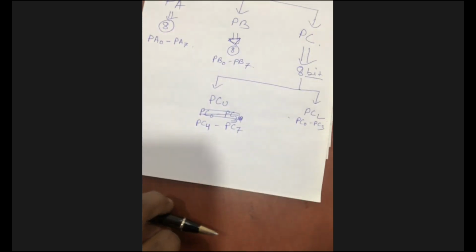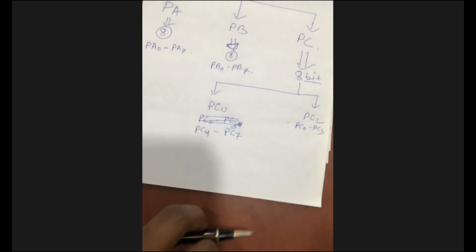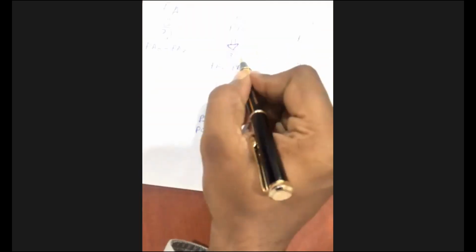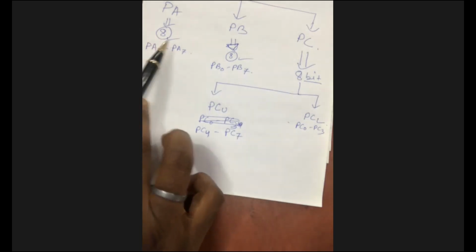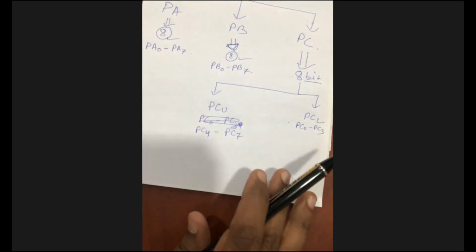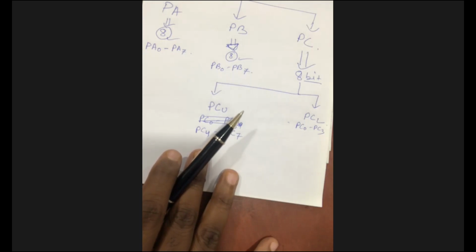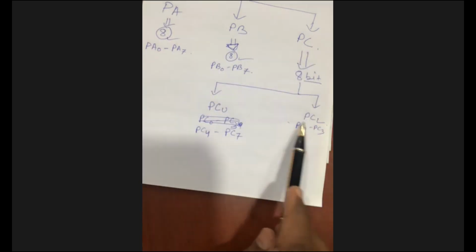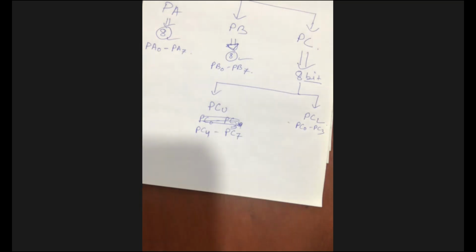So with the help of the 8255, we have two 8-bit ports and two 4-bit ports. Means we have 3 ports or 3 hands, whatever you say: port A, port B, port C. Port C is divided into 2 parts, port C upper and port C lower. Is it clear? Yes, sir. Very good. Port A, port B and port C.